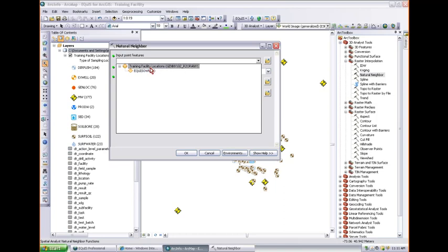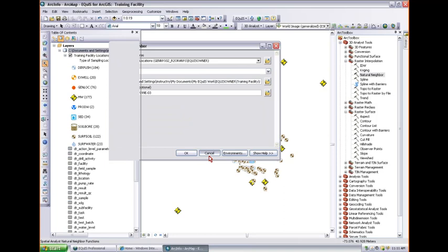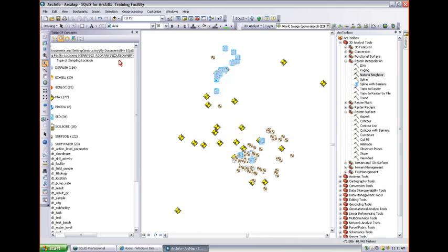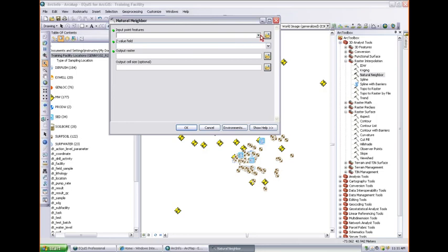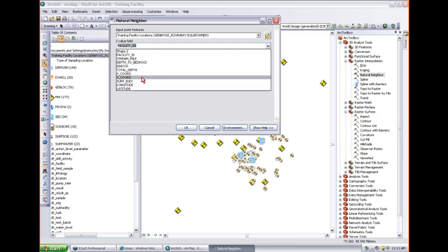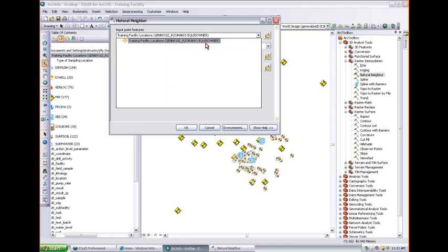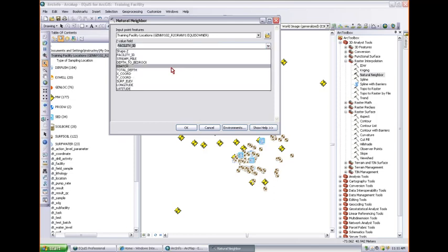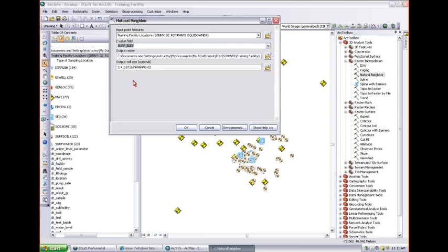So here I find an issue: it doesn't like our space in the layer name in that geoprocessing tool. So I'm just going to remove that. Run this again. So you just pick your input layer. What field do we want to contour? I picked the wrong one. We wanted to do water level data, right? But I'll just do it on the, this is a good way to get a quick and dirty surface elevation from your facility. You can just do a contour of the surface elevation that you have from your surveyed points, and that's the rough estimate, right, of your ground.